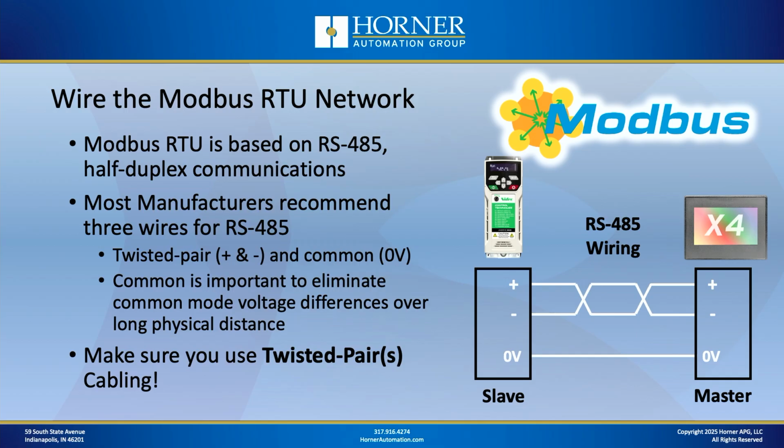Why do you need the common? Well, RS-485 devices can be several thousand feet apart, which means they may have a slightly different ground reference. And if that ground reference is different enough, then there will be communication issues due to common mode. So use that extra common conductor.